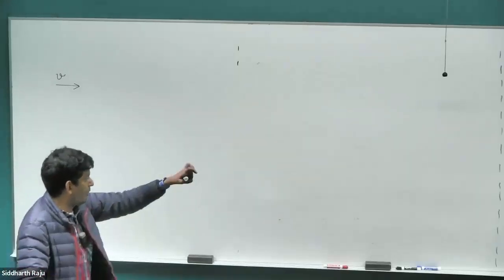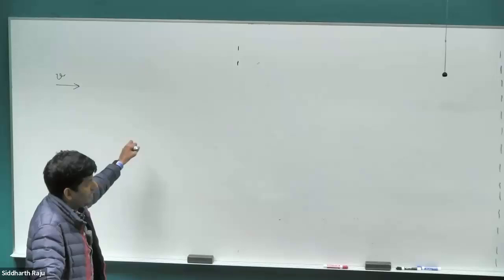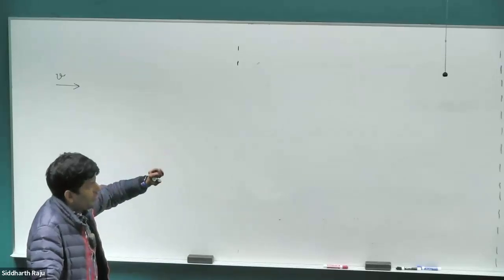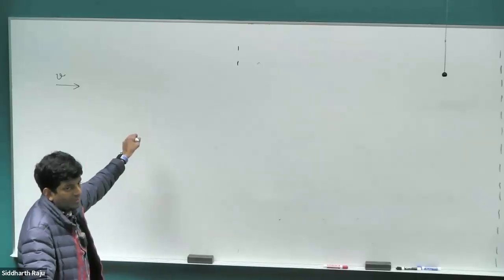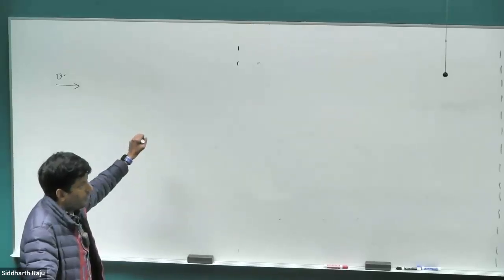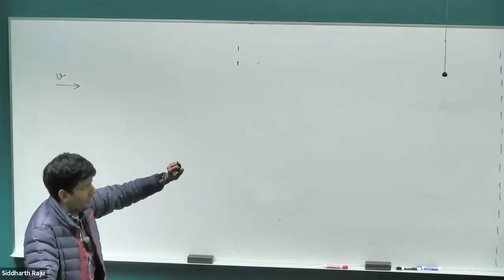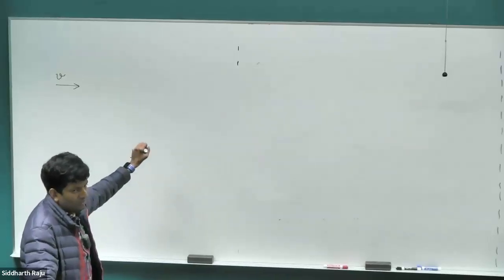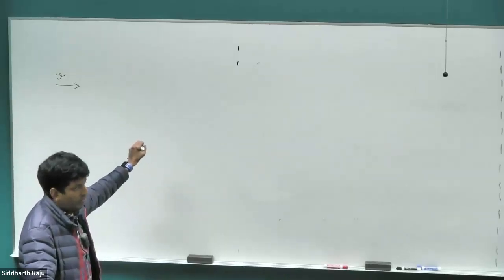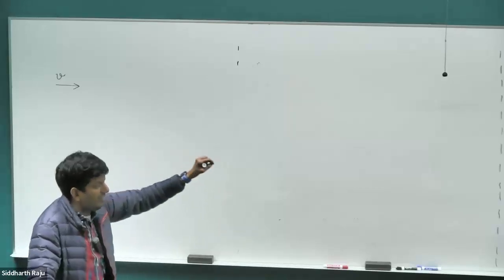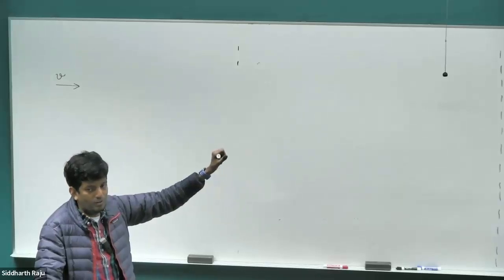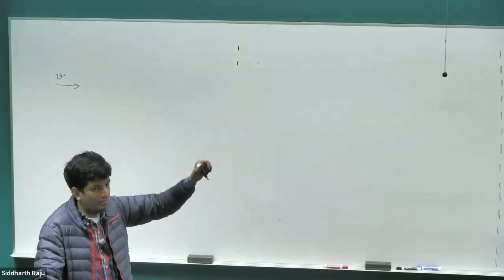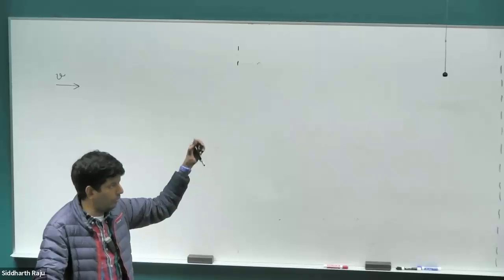So in Simulink, there are two options. You can either model it using power elements, or you can model it as purely mathematical elements. We want to stick with modeling with mathematical elements, as we'll see in a minute why. We get a lot of advantages. It's exponentially faster to do the simulation when you have mathematical elements. And second, when you go to AC motors, the inductance starts to change. It becomes very hard to model things as a variable inductance in power toolboxes. So you want to do it mathematically.